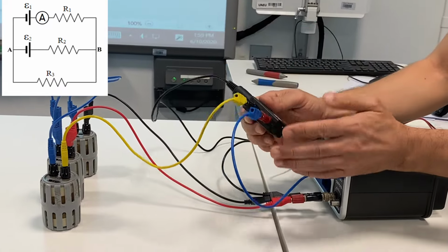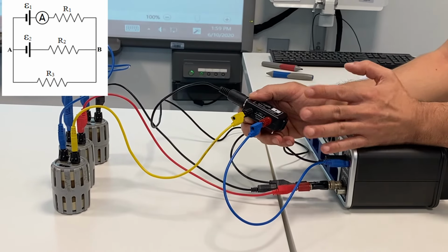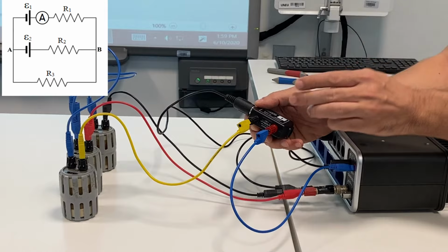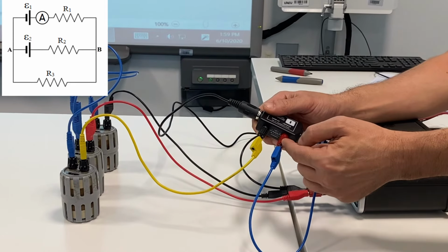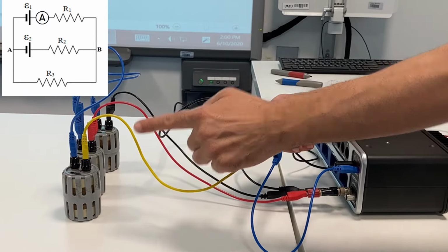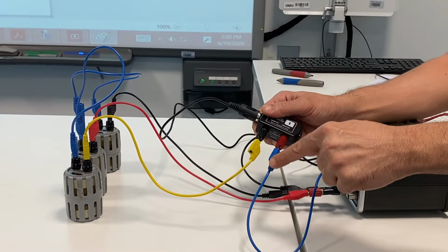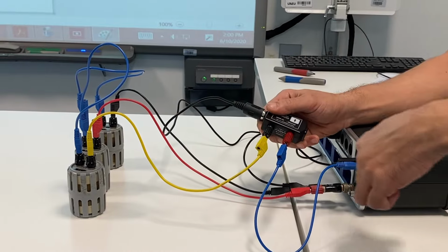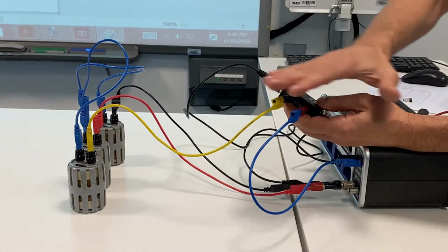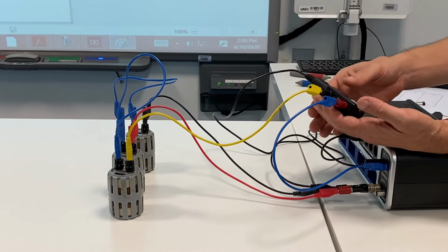Now you don't have to connect the red with the red and the black with the black, because we will pretend, at least, that we don't know the direction of the current. Now, if you get a positive reading from the current sensor, this means that the current enters the red side and exits the black side, which means that it is moving in this direction. If you get a negative sign, this means that the current enters the black side and exits the red side, which means that the current is moving in the opposite direction. So this way you can measure the current in the first branch. You will repeat the same process for the second and third branches.